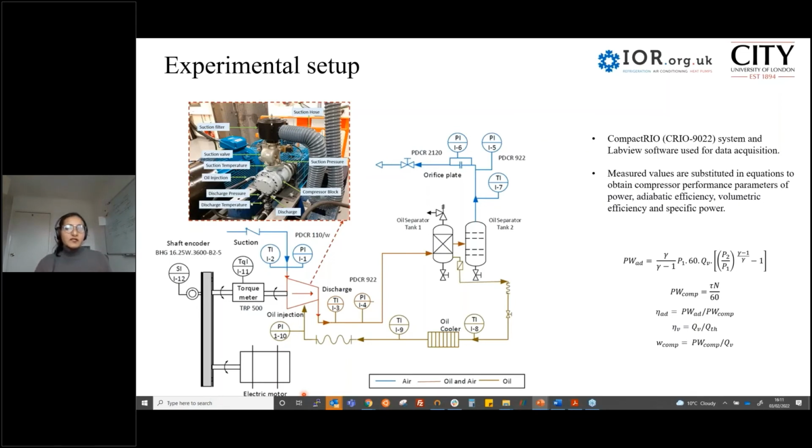So this is the compressor in the test rig. You can see that the injection is on the female rotor side, and this is a very standard sort of injection for an industrial compressor. We designed compressors of different sizes, and for all of them we had the injection port on the female side. This is one injection port, and that's a standard compressor design. So here we are going to look into whether that's a good design.